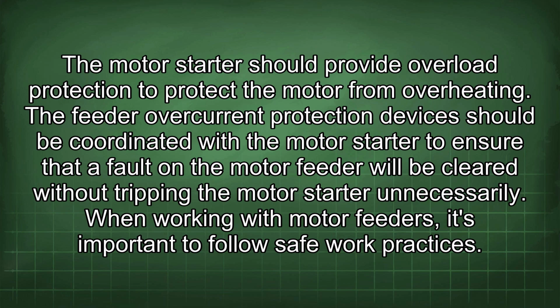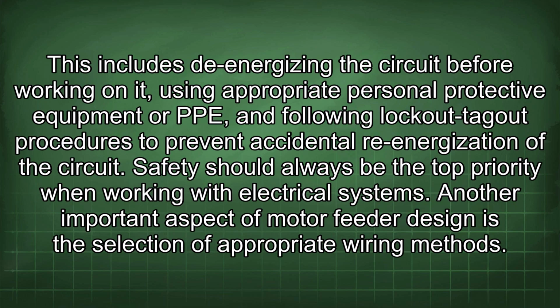When working with motor feeders, it's important to follow safe work practices. This includes de-energizing the circuit before working on it, using appropriate personal protective equipment, or PPE, and following lockout-tagout procedures to prevent accidental re-energization of the circuit. Safety should always be the top priority when working with electrical systems.